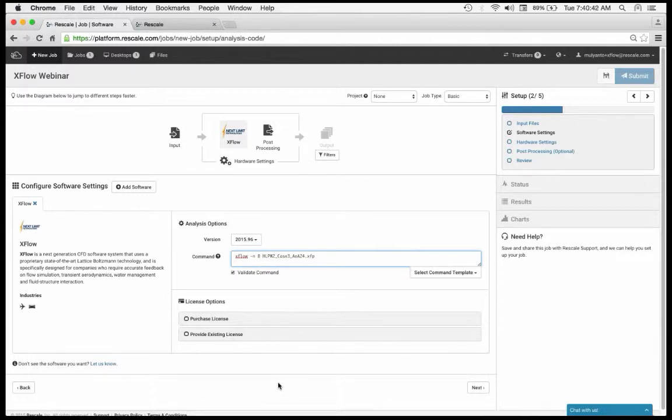It'll then run the generate domain command to generate your domain depending on the number of nodes you choose. And lastly, it'll run the flow solver. It'll pick the correct flow solver depending on what flow solver you chose in your case setup.